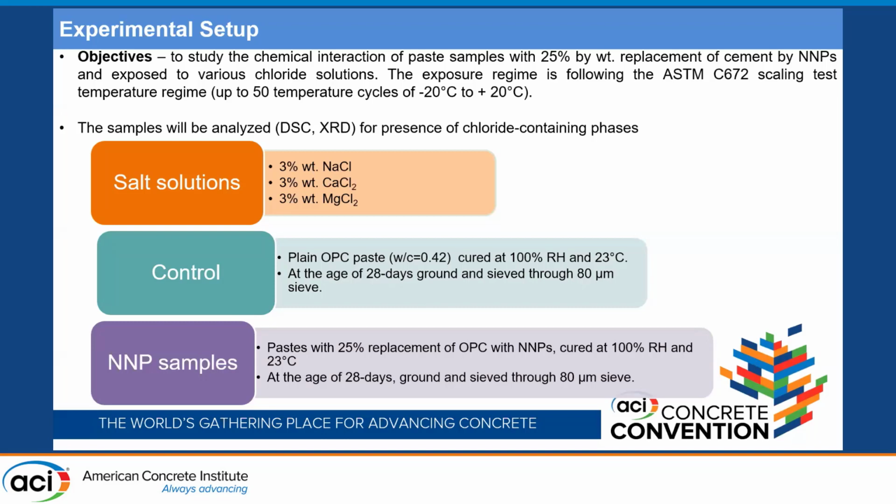In terms of chloride binding, I'd like to emphasize the formation of less deleterious, or even non-deleterious, and more stable chloride-bearing phases, for example, Friedel's salt.